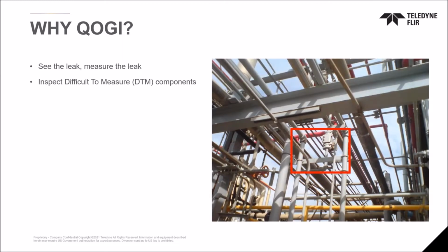Within the industry, you're going to hear the letters DTM, in particular in the United States regulatory framework. They talk a lot of DTM, and what that means is difficult to measure components. In a regulatory framework, there is no requirement, or there is an exemption with DTM components, so that you do not have to measure these components that might be at a great distance away.